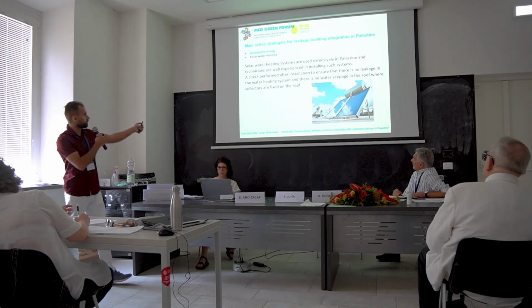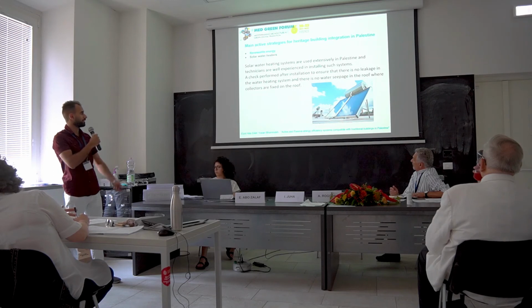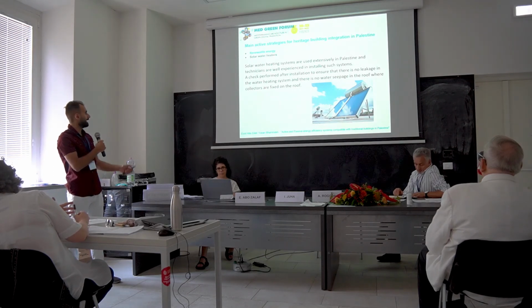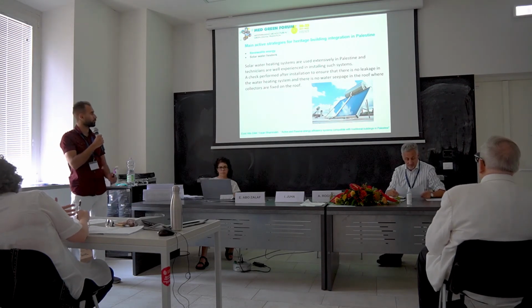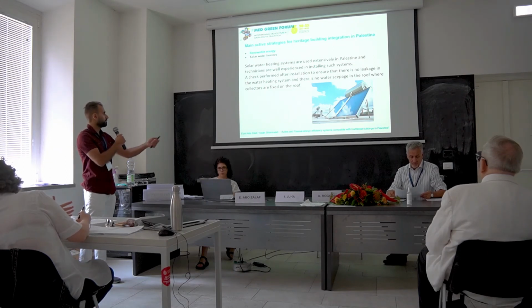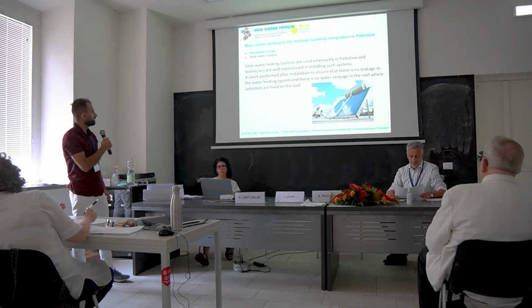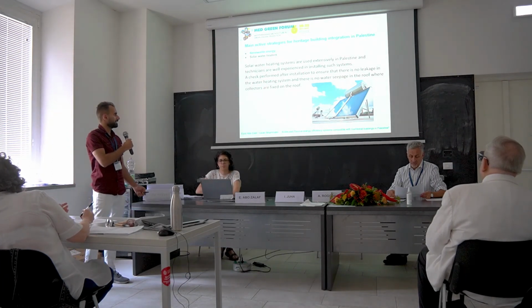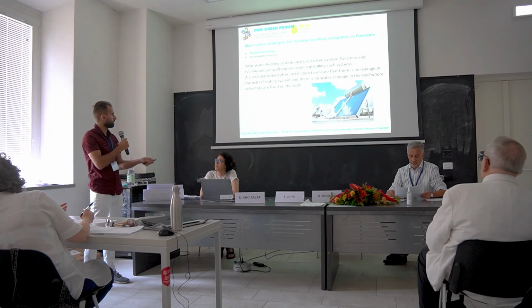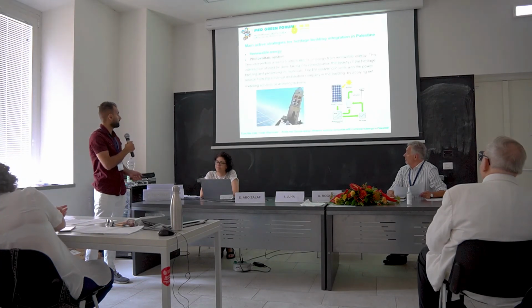Solar water heating systems are used extensively in Palestine, and technicians are well experienced in installing such systems. A check should be performed after installation to ensure that there is no leakage in the water heating system and no water seepage in the roof where the collectors are fixed. The last one is the photovoltaic system.